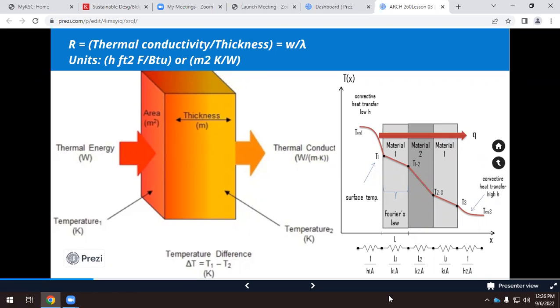It's very light. It's not heavy at all. Very light. And probably this thickness of this thermal insulation has the same thermal resistance as 2 feet of brick. That's perfect. This is what we need. We need something light because moving this is very easy. Moving 2 feet of brick, you need a lot of people to do that. It's very light, it's very cheap, and it has a lot of thermal resistance. So we need a lot of this material inside the walls.